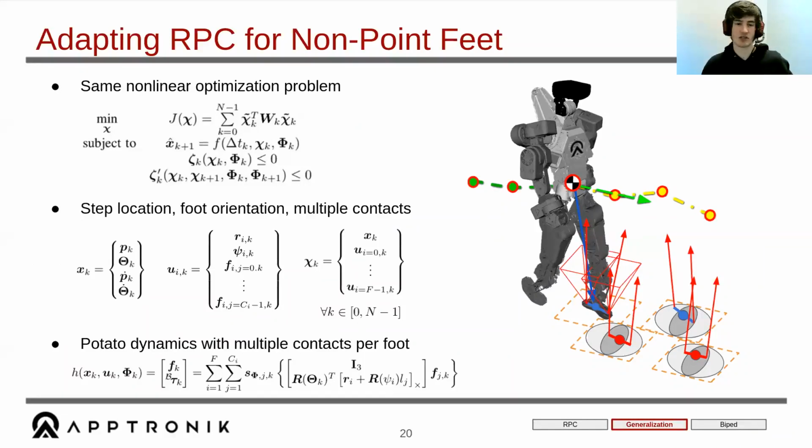But since this is a nonlinear optimization, you know that if you place the foot forward and push, and basically this interaction of this R cross F term between foot placement and forces, you're able to get the robot to turn in yaw, especially because you have a predictive controller. So you can put yourself into an unstable position for one time step, knowing that in the future you're going to be in a stable position. So turning in yaw, even walking for a point foot biped is always unstable, but you know you're going to be able to stabilize or compensate in the next footstep.